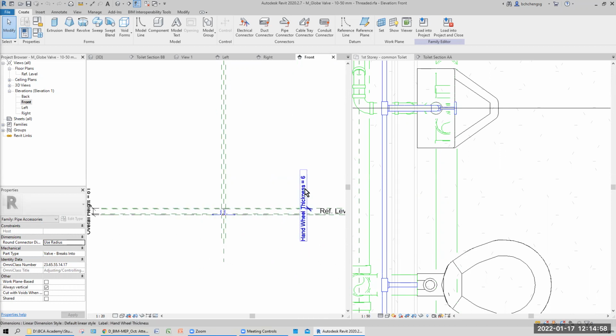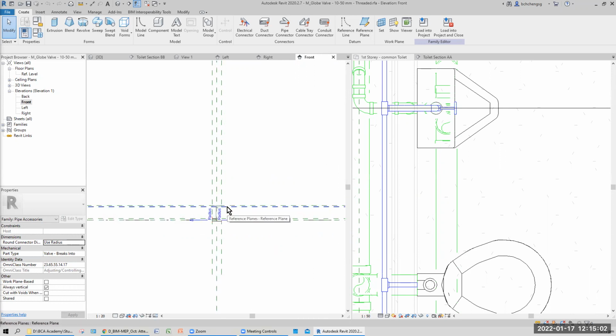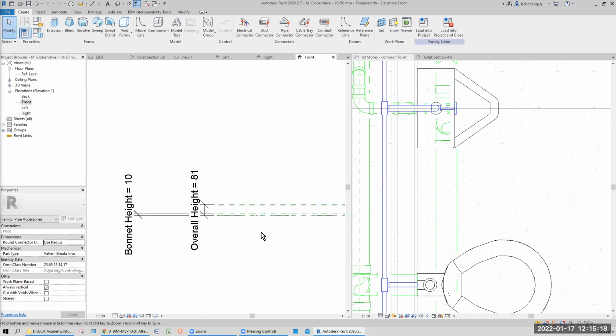The wheel thickness normally is not 6 mm. For a press button, normally slightly thicker. It could be 10 to 15 because it's a cap on. So this detail I don't want to change. I just want you to change this length here, which is more important. So this length and this controlled together is what we call your overall height. So I need to change this.